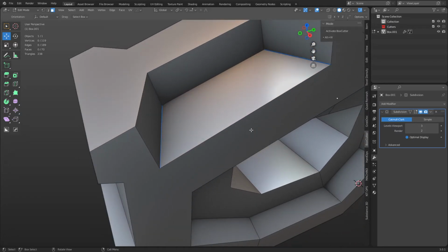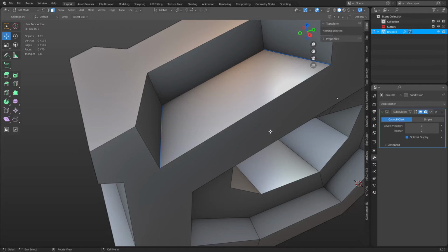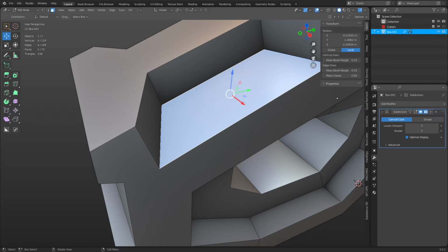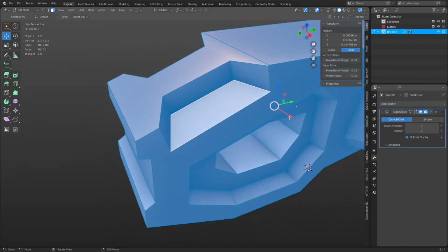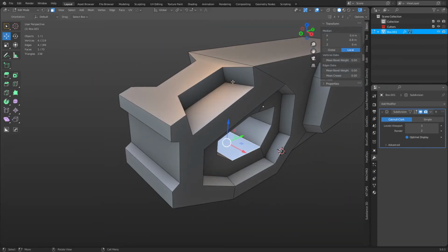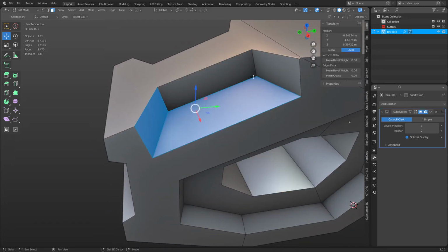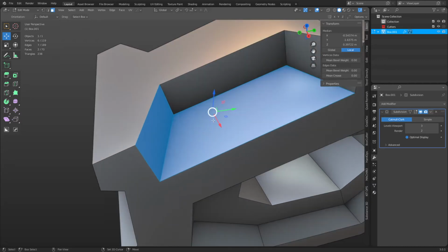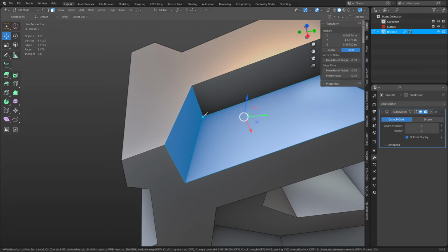And part of this correction, I want to make sure I press N, bring up item, this object, edit mode here. Oh, interesting. Okay, I'm gonna select it all real quick. Turn mean bevel weight down and mean bevel weight down there for vertices. Okay, just getting rid of those little blue lines. And more or less at this point, I can just go through and start changing things and correcting them the way I want, manually using a knife tool or doing insets or extrudes or whatever the case may be.